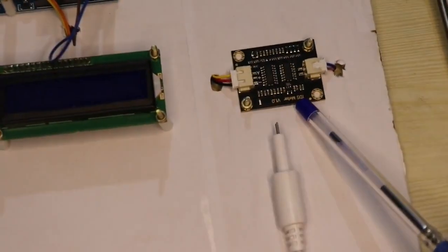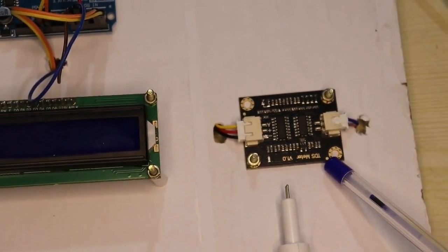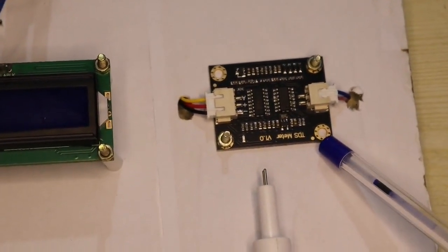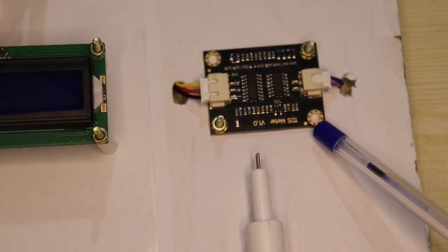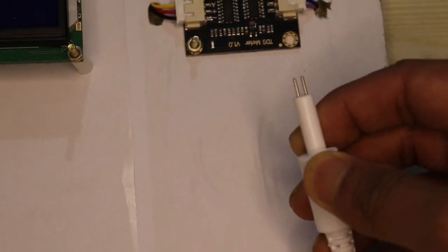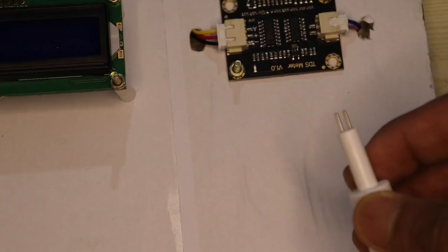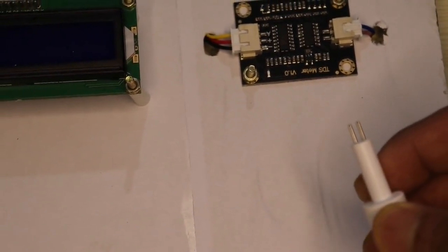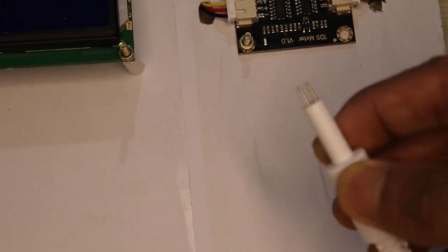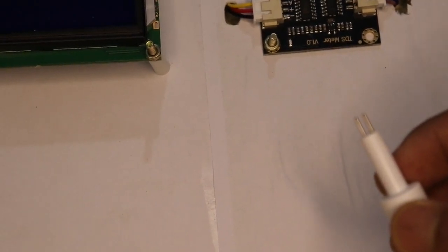This is the TDS sensor. TDS means total dissolved solids in the water, which we are measuring using ppm. ppm means parts per million. Here we can see there are 2 electrodes which are equally separated. Using these electrodes we can check whether the water is highly conductive or less conductive. Based on the conductivity we will decide the TDS, and we can check whether a number of things are dissolved in water, like iron and other things like aluminium and other oxides.